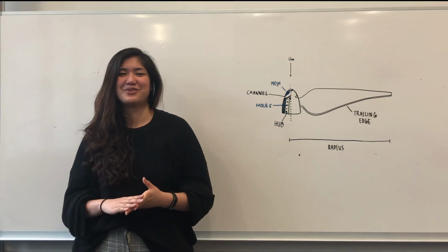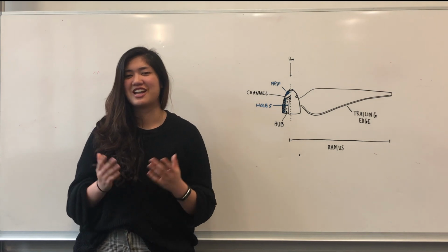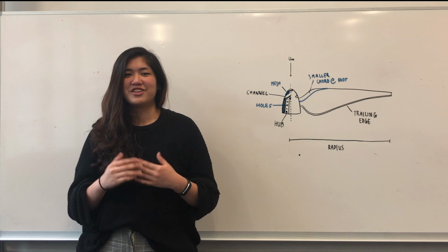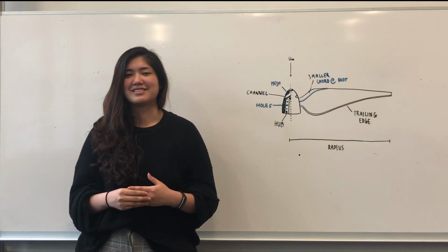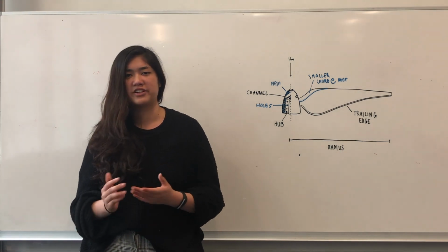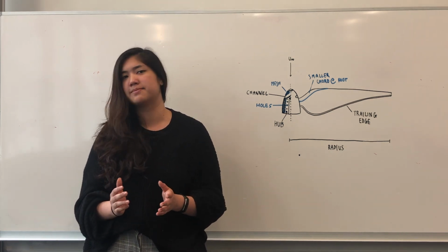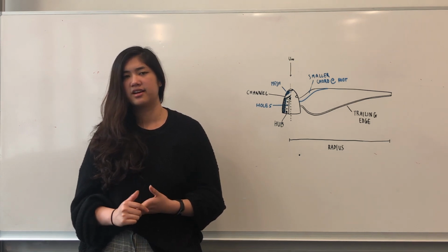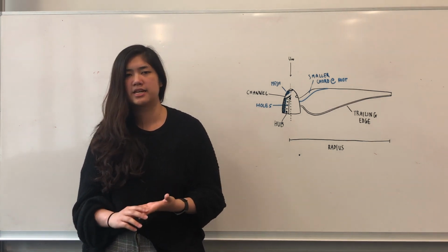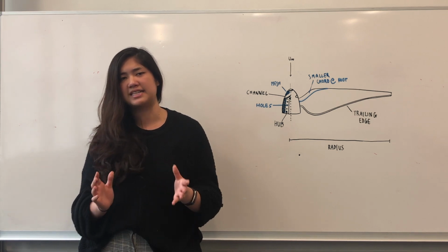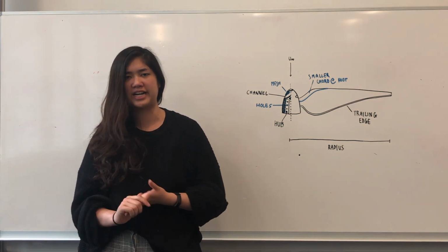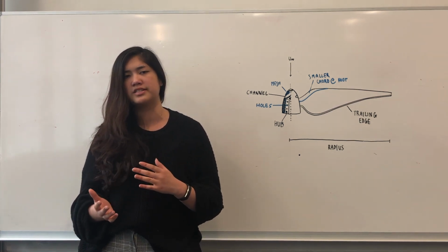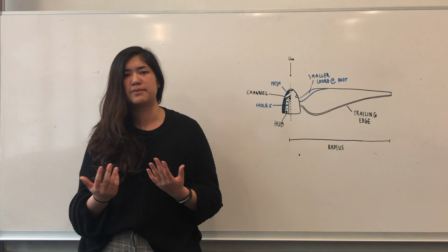Another design feature, which had too large of a safety margin, was the large cord at the root, which contributed to the drag. We could sacrifice the structural integrity for a more aerodynamic design. Since our turbine radius was very small, the trailing edge was too thin and couldn't be printed. Thus, we had to add material to the edge to be sanded later. However, in the end, our fear of breaking the turbine resulted in very badly sanded areas and an inaccurate trailing edge. To solve this problem, we could increase the thickness of the trailing edge by slightly increasing the turbine radius, such that it can be printed accurately.